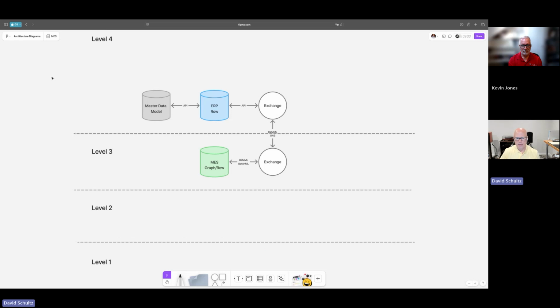So when we get into level 3, again, this is going to be your manufacturing execution system. Within the ISA 95 standard, there are 12 functionalities that exist. Most people are familiar with MES through what's known as the Core 4, and that's, I think, because MES has largely been sold and marketed through some sort of functionality, whether it's OEE, downtime, or material genealogy, track and trace, or statistical process control. Those are the types of functions that you're going to find in an MES.